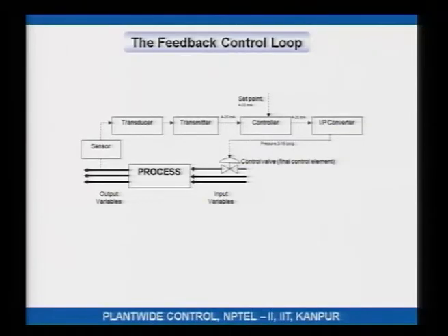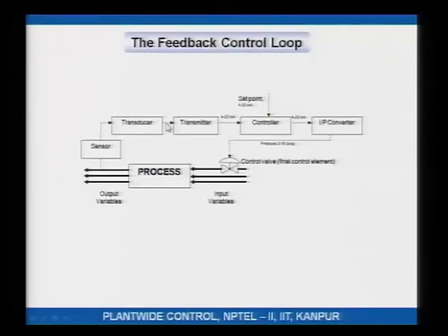So, the transducer gives a signal which may be in volts, millivolts, etc., but this signal needs to be converted into a signal that can be taken by the controller. So, the transducer electrical signal is converted to a 4 to 20 milliamp signal by the transmitter. The controller does its calculations and then it outputs a 4 to 20 milliamp output signal.